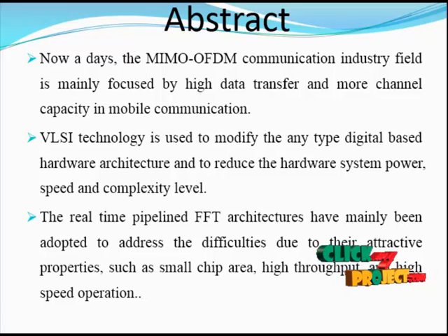The Radix-2 FFT architecture has a common observation that one half of the data does not involve complex multiplication at all, while the other half indeed involves complex multiplication. Hence, it has the opportunity to reduce the arithmetic resource of conventional complex multipliers by a factor of 2, leading to 100% utilization. It is ideal for two consecutive complex input data to contain a complex number which needs to execute complex multiplication. If so, we can minimize the reordering memory requirement by achieving the above objective that reduces 50% of the arithmetic resource of complex multipliers.